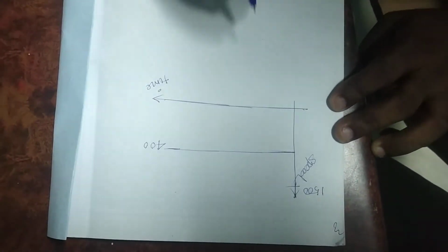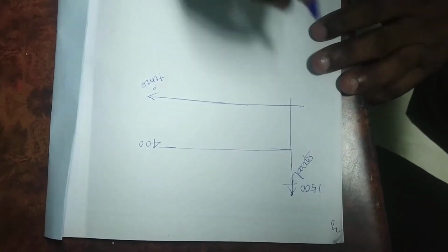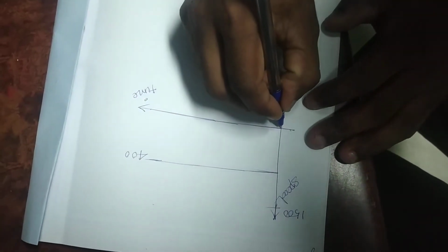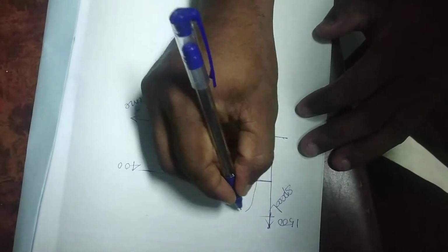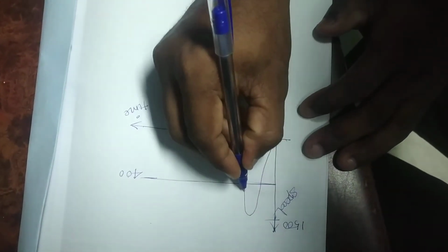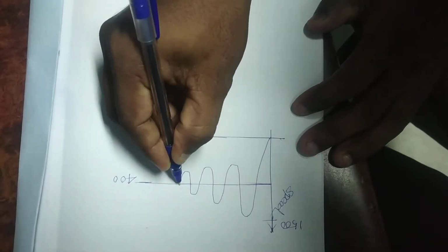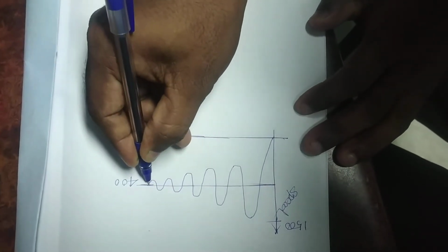After giving all the input values, the motor starts to rotate from 0 rpm to maximum rpm, then it comes down, then goes up again like this. After taking some time, it reaches 400 rpm. If the Kp value is 3, it takes this much time.